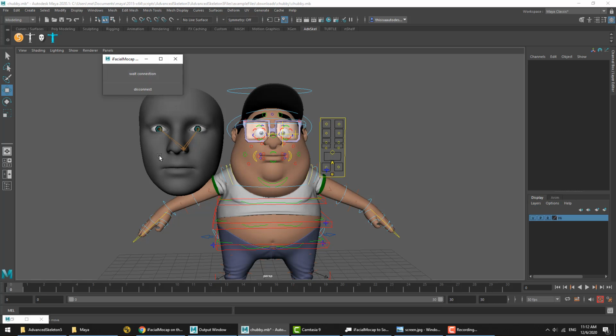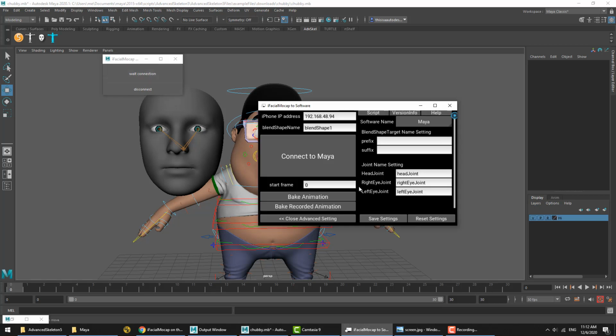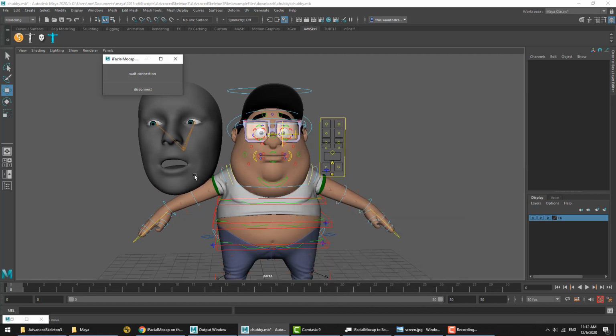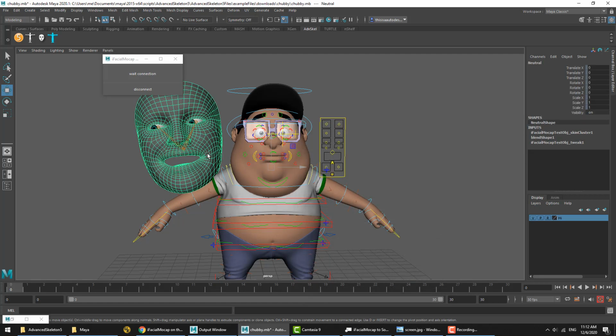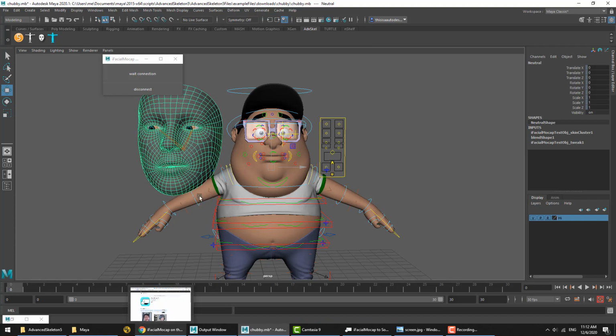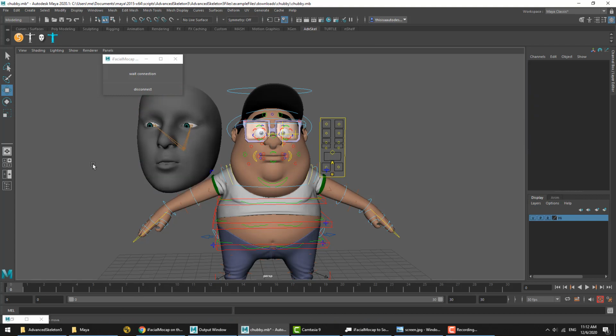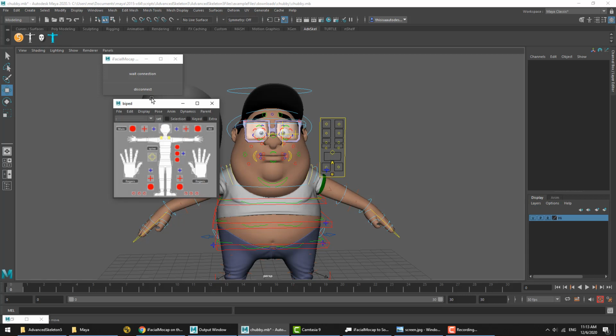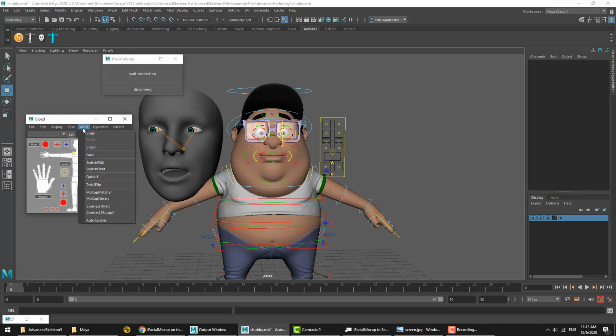And then we'll connect this face again to the live stream. There it is. So here comes the trick for connecting this face from iFacial mocap onto advanced skeleton. And the workflow is the same for all the various apps that use the ARKit development tools. We open the selector, and from the anim drop-down menu, we'll choose Connect ARKit.